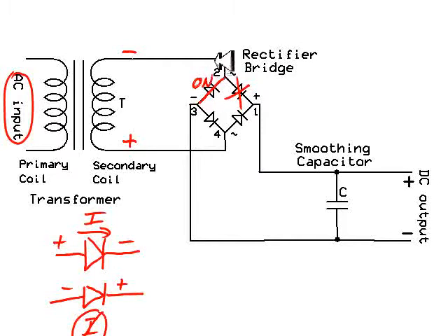The other wire of the secondary coil of the transformer is positive. It's connected to these two diodes here, and therefore this one will be on because it's positive on the back end of the diode, and this one will be off. So the positive voltage ends up coming out here, and the negative is connected here.